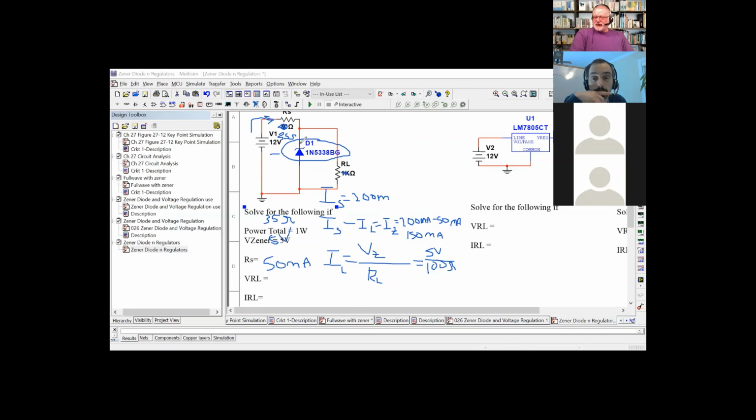Okay, so then I have to go back to the first diagram that you drew, which had just the Zener and the load in it and the battery. Yes, that was just me doing an example. The source voltage was 10 volts, and we talked about 10 volts going out to the load. It would be a little less than that, just a little bit. If the source voltage is 10 volts and our Zener was 10, then you would get just under 10, about 10. Okay, so the stuff that's parallel to the Zener is getting the voltage that the Zener is rated at. Yes, as long as the Zener is getting that much voltage or more from the source.